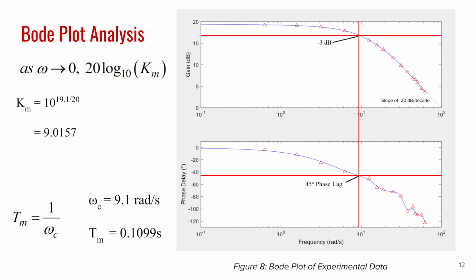The difference between the constants found from the time domain analysis and the frequency domain analysis arise from the simplifying assumptions we made for our model. These assumptions include assuming that friction is negligible and inductance can be ignored. These assumptions have a much smaller effect on the time domain analysis because the system eventually reaches steady state, so assumptions such as the inductance being 0 are valid. In this case, however, the system never reaches steady state because the input is a sinusoidal wave.